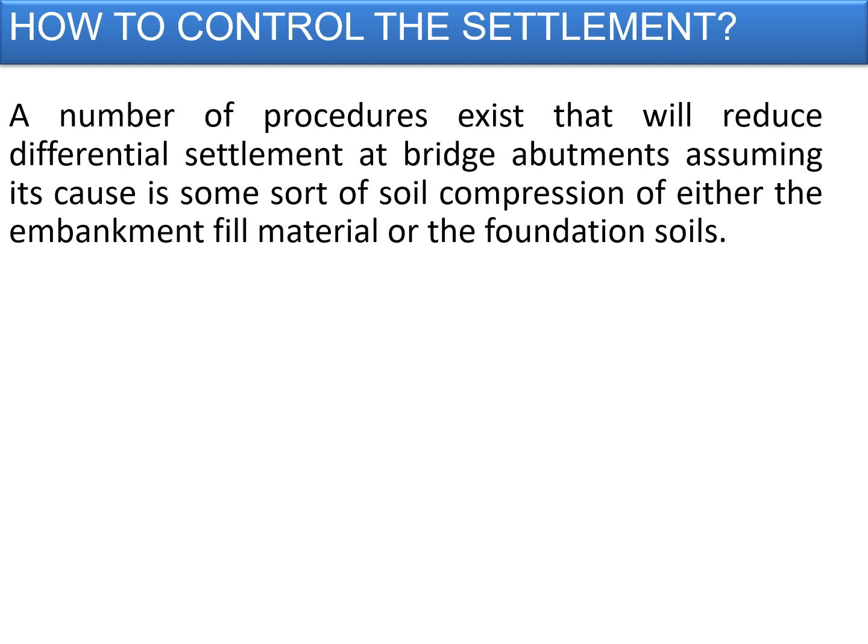Sometimes the weep holes provided on the walls of the abutments, which are left unattended without a geotextile membrane from the backside, allow the soil to move out of the weep holes, thereby allowing the approach slabs to settle, because there will be unforeseen voids created between the bottom of the approach slab and the top of the soil within the approach slab areas.